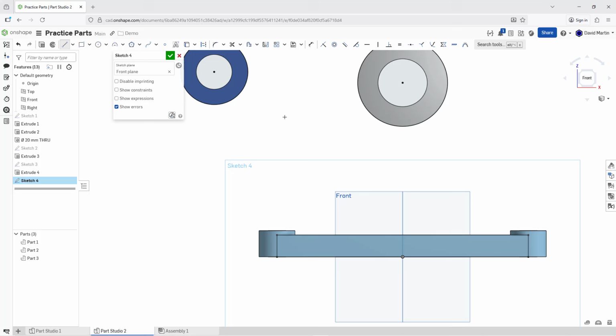By doing that, I should be able to snap. So I'll sketch, yep, I am snapping in here. And then it's going to be at an angle. So I will click over there. Let me hit the escape key. Let's throw in one of our constraints. I want to have tangency from the line and the cylinder.